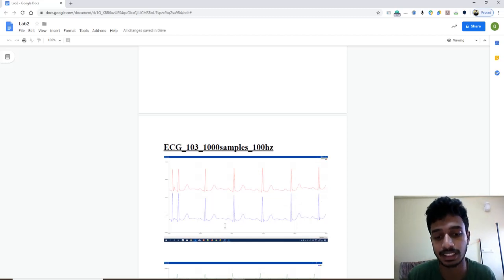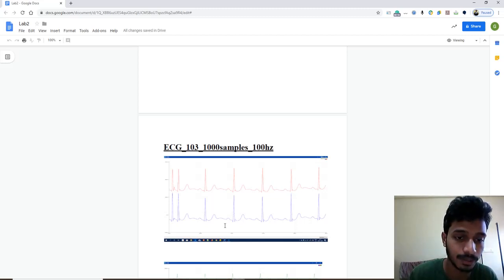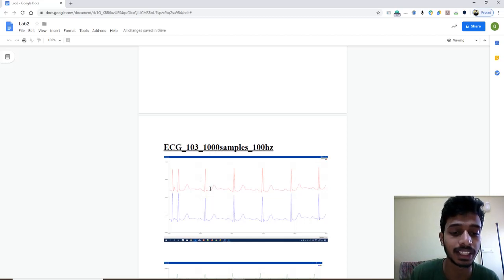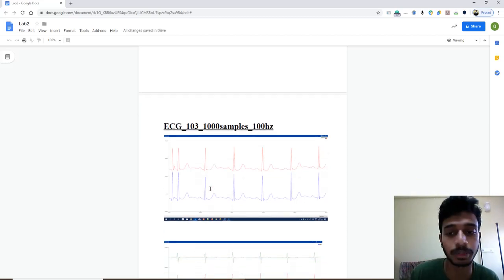There are many spikes. So if we pass this through a moving average filter for smoothing, and if the order is high, say 8, it averages the present input with the past 8 values. So as you can see, if I average this with the past 8 values, it will be smoothened or flattened. So I can't retain this spike. In order to retain this spike, I need to reduce my order.